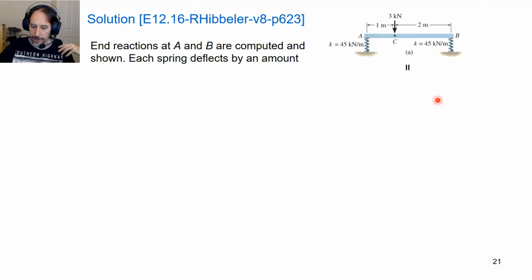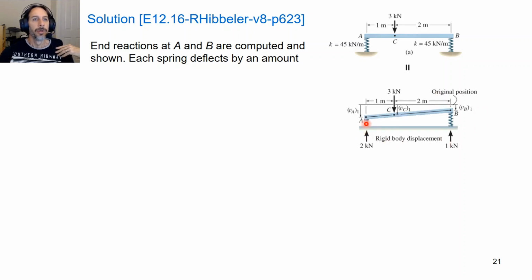Okay, so how did you go with that? All right, so I've shown here that we're going to get a rotation that looks something like this. Now, why is that? If we do our equilibrium calculations, work out our reaction forces, right, because this force here is closer to the end A. So do sum of the moments equals 0 for equilibrium.